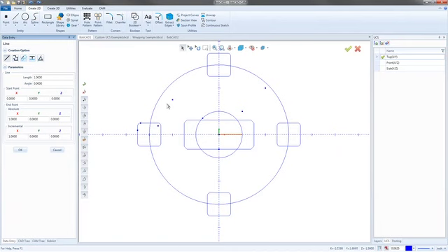But now if I go in, I can actually click on a point and say, I want to go there. And again, our construction geometry will pop up. I'm going to turn that off because it's kind of annoying. So you'll see we still have our full range of sketch. It did snap onto the point, which is huge. In the previous versions, the sketch function didn't snap onto points, or at least it wouldn't always snap. Sometimes you'd get lucky and get it close, but for the most part, it wouldn't snap. It was not a good way to create a line that joined between 2 locations.